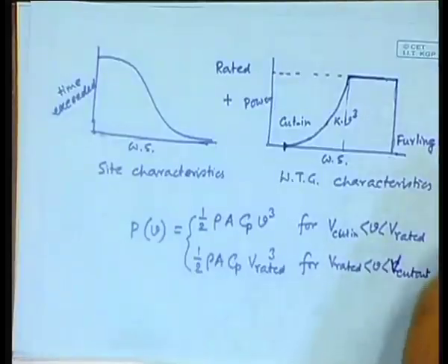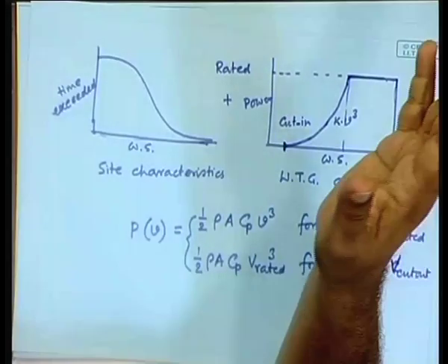So, if you are having the task of installing a wind farm in a particular spot, and there are say 20 different vendors coming to you trying to sell their wind turbines, how will you do the choice? How will you go about it? Number one, first measure the characteristic there. From there obtain the statistical distribution. Find out which characteristic it is most closely matching. That means, in the Weibull distribution, set the variable parameters properly. Then you can approximate it by the Weibull distribution.